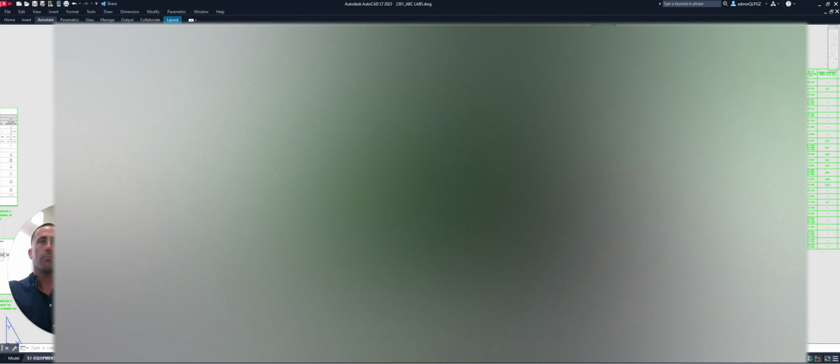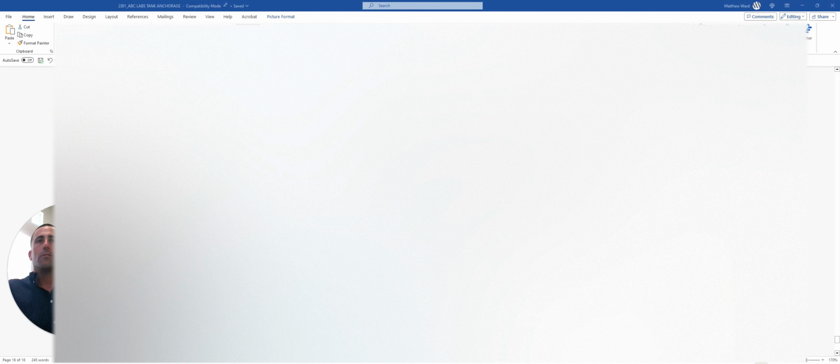Alright, so we're going to step away from this and go back to our calculation report. So here we are back at our calculation report, and the next item here is the concrete slab. One of the things I said earlier is let the template be your guide. The template walks you through the steps of the things you need to check. So now we're going to design the concrete slab. And as you can see here, I like to design my concrete slabs using InterCalc. But before we get to that, I'm going to input a few pieces of information here.